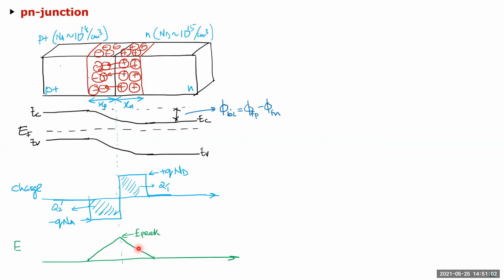So now if I plot the electric field across it, it is essentially the derivative of this potential. Because the charges start here, obviously the electric field is 0 here, and the charges are increasing, so the electric field starts increasing. It peaks at the very junction. Then the electric field starts terminating on the negative charge, which means it slowly decreases, and it is 0 after the depletion area, right? And I haven't drawn to scale here. Again, this is not exactly linear.